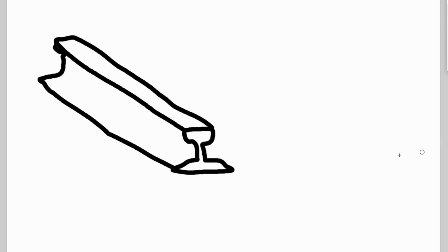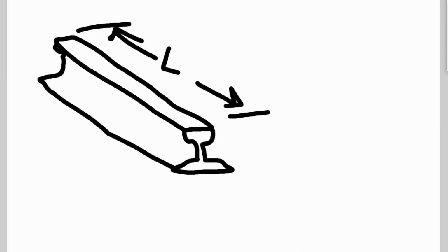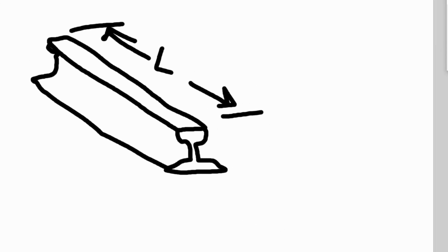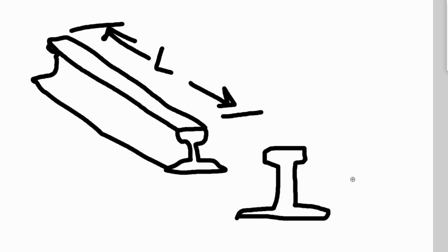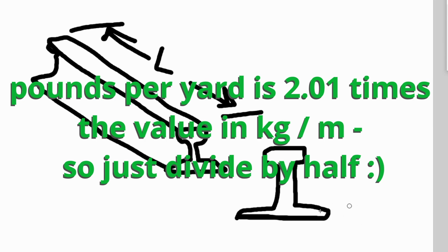There's another important factor about the size of rail. We talked about the length here. There is a considerably important and also considerably American way to measure the weight of rail, which is the overall size of the rail. It is measured in pounds per yard. So for all of you that are outside the United States, that is pounds for every 3 feet, which ends up becoming something roughly like pounds per meter. And remember, a kilogram is 2.2 pounds. So I'll try and remember to give you guys the conversion on these things.